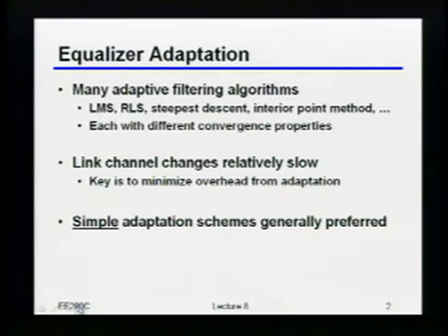But there's one important thing to keep in mind from the standpoint of, let's say, at least this class, or at least high-speed links, which is that even though we don't necessarily know which channel we're operating on, generally the changes in channel are relatively slow. Right? In other words, it's usually like, okay, I built this link once, and then I took that chip and plugged it in, and then it's sitting there in that same channel or same plug for, practically speaking, forever. Now, to be fair, even if temperature and humidity change, that will change the channel characteristics a little bit.